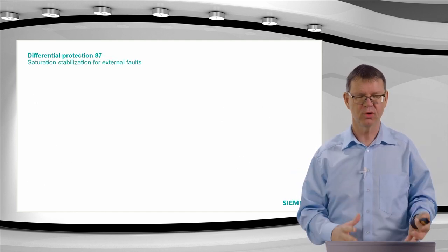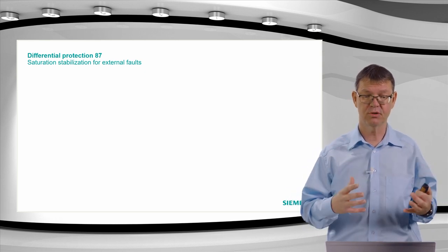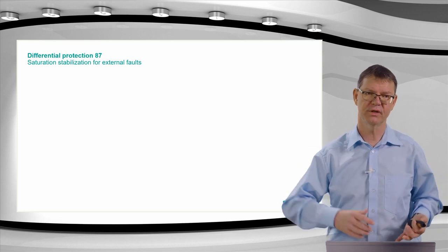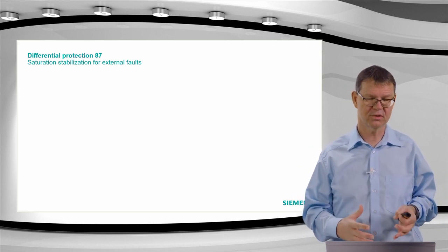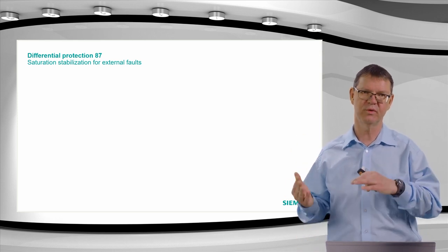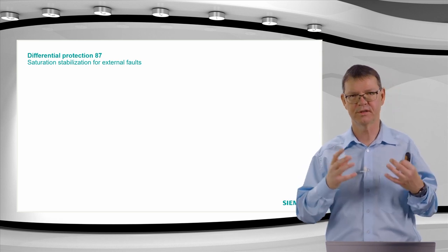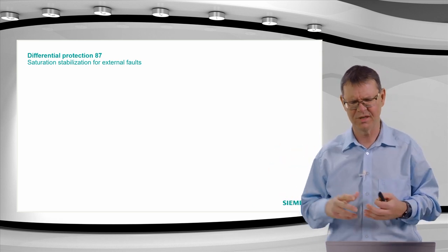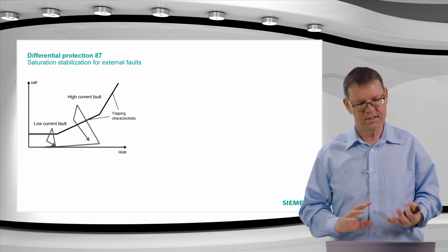Yeah, when we talk about differential protection, we talk a lot about stabilization against external faults, so that I don't have an overfunction for external faults. In that case, for the motor protection, we can forget external faults and substitute that with the starting current. So we need to be stable during the startup of the motor because, as I already mentioned, we do not really have external faults. Okay, this is what we normally do.